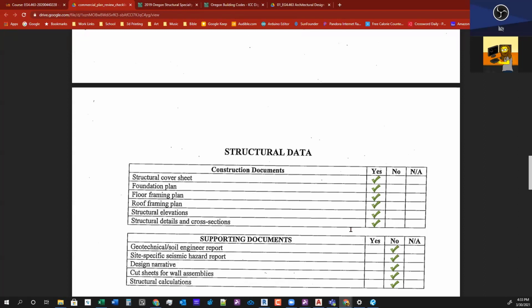So similar to AutoCAD, where you have an external reference, we'll have an external Revit link of our structural model. But we're going to create both, and then we'll link our structural model into our architectural model.